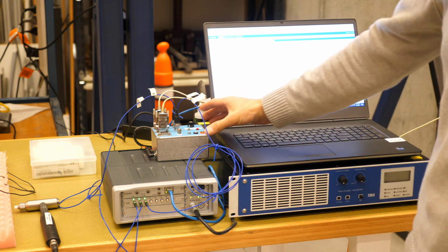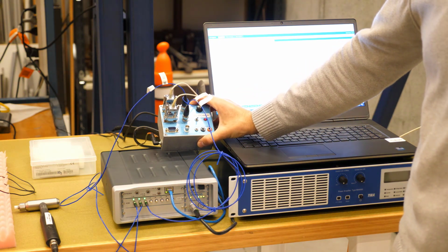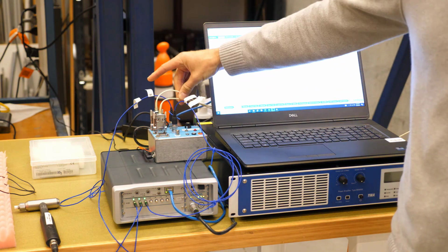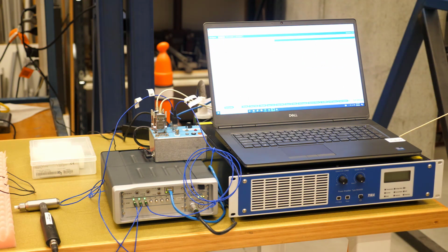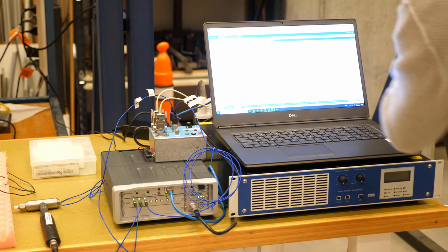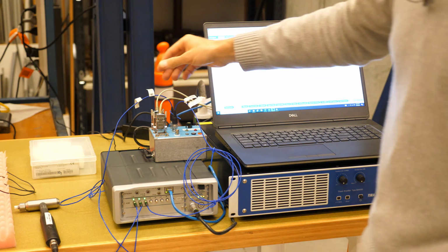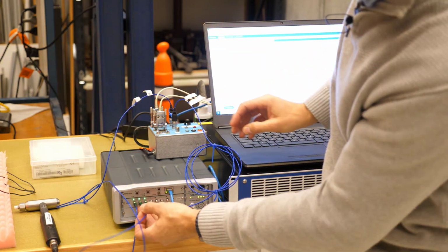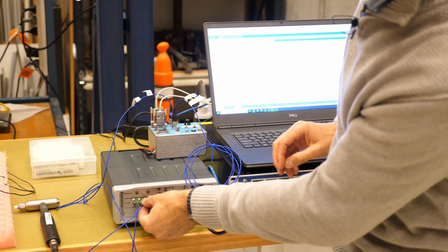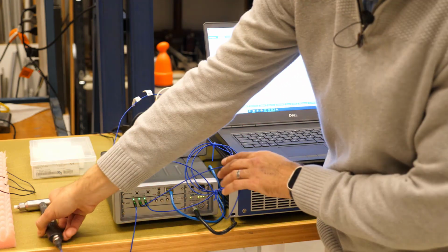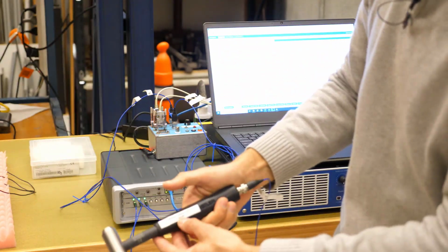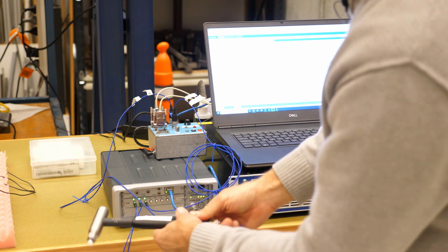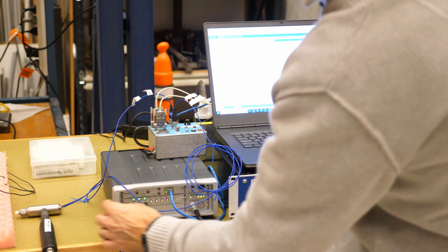Here's a little bit of a close-up of the instrumentation that I'm using. This is the power supply for my 2 DC response accelerometers, which I have mounted to the tower and which are routed by cabling over here. They are then connected from the outputs from the power supply into these 2 channels, 2 and 3, on the data acquisition system. On channel 1, I have my instrumented impact hammer with a nominal sensitivity 2 millivolts per Newton, which I've also defined in software.